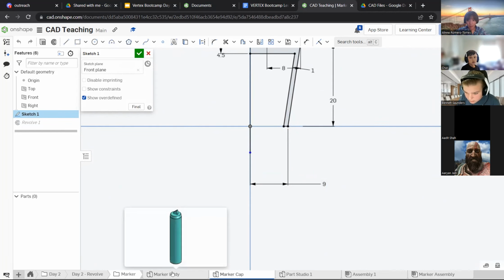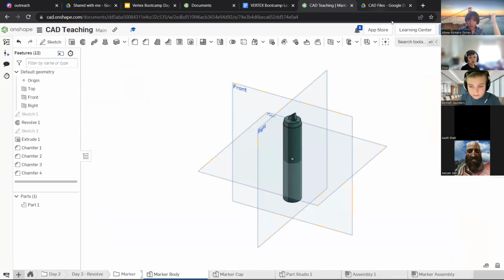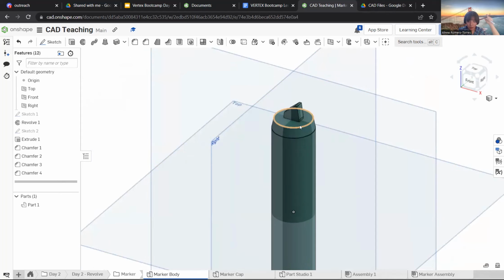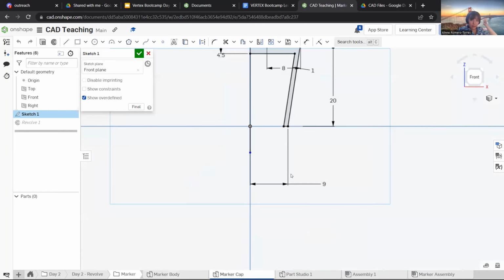If you aren't sure what your marker's radius is, you can go back into your sketch. Looking down here, there's a measure tool, and when you press something, say I want to know the thickness of this, because I want the marker to go on that part. It says it's 20, so the diameter is 20, so I can have the radius of my cap be 10. Or if I want the cap to fit on this piece, here I have to deselect. It says it's 18, half of 18 is 9. So I can make sure my marker cap fits on that, because when I go into my dimensions, I'll set this to 9. And that makes it really helpful.